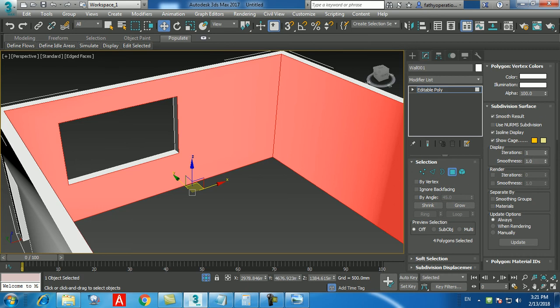Now, when I make Pro Boolean, start picking, I'm picking this one. Now, you should have edit polygon, you do not have it. Pro Boolean is a very, very important tool. So it will remove everything that it can. So now again I have to convert it into editable poly, and when I select polygon, it will select.